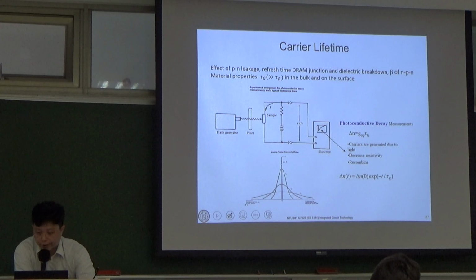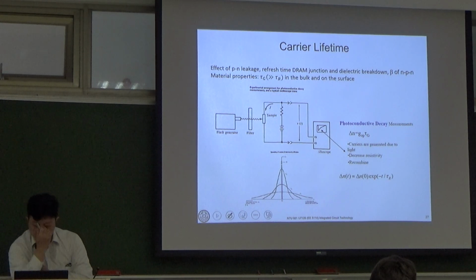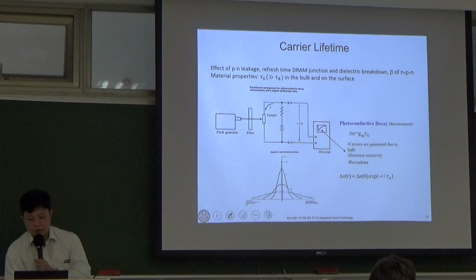We can infer the quality of your material or your dielectric film. Or we can measure the capacitor breakdown. Or we can make a transistor. You can see the beta, like this NPN transistor, the current gain will be affected if you have some defects inside. For this diode curve, we can check if there's any leakage inside your junction. So that's the device level that we can make.